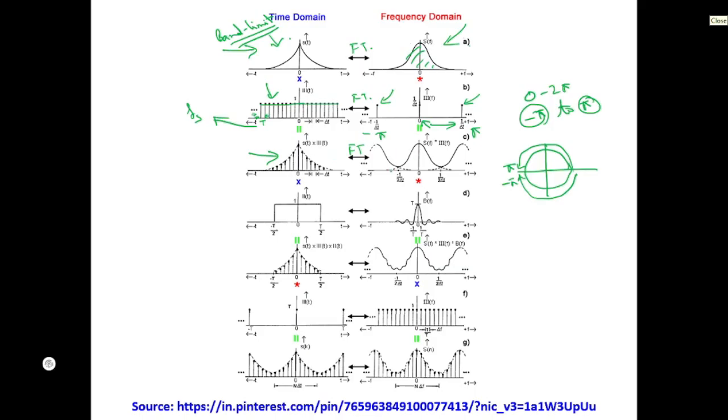Because of this, if you see over here, there is mixing of the frequency components. So why do we want to band limit? We want to band limit because we don't want this mixing of frequency components. This was your original frequency content from here. Now due to the repetition, you have it like this.